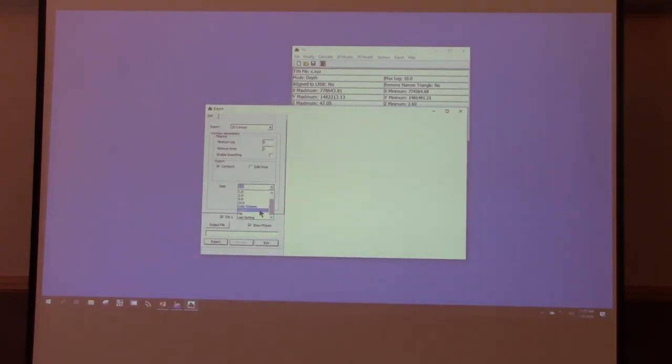If you go to the custom setting, you get to specify the contours that you're doing. It doesn't mean if you put 7.5 that it's going to go every 7.5 foot contour. It's going to be at 7.5. 7.5 is going to be your contour level. It doesn't assume that you want one every 7.5 feet. Does that make sense so far? If you want multiple contours, you would put in 7.5 space 15 space 22.5. That makes sense? That's how you're going to get those contours.